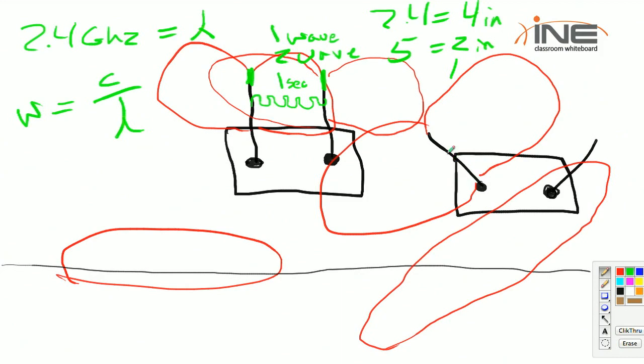When you begin turning them like this, not only do you change the radiation pattern, but you skew the amount of wavelengths between each other, and they begin to have issues with collisions instead of working like they should with spatial diversity. So it's actually important with dipole antennas to keep them in an upright position. So they should be basically pointing towards the sky.